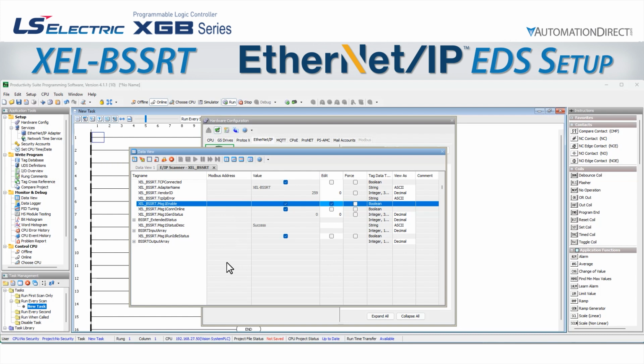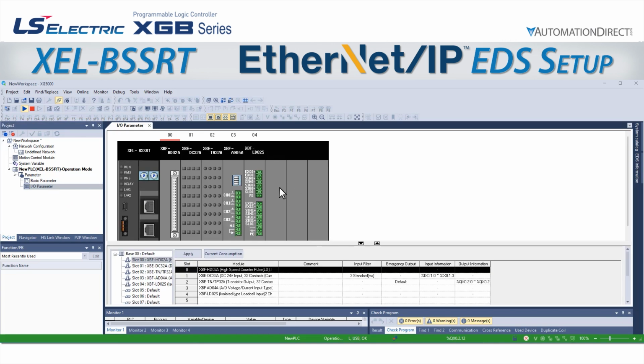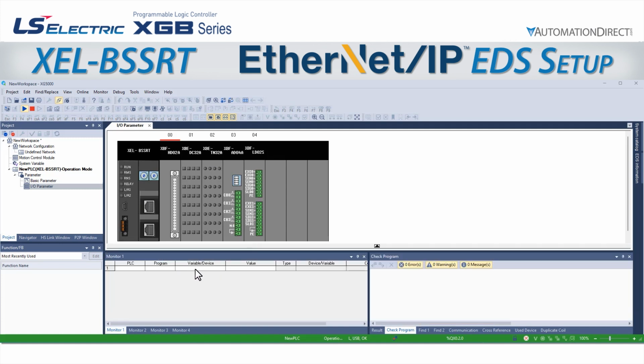Let's try and turn on the first output of our digital output card. If we go over to XG5000 and then to the I/O parameters screen, which is already open in our case, we see that the TN32A output card is in slot 2, which is the third slot, and that the first output point is variable %QX0.2.0. Let's add that to the monitor window so we can observe when the module turns it on and off. We will also go into monitor mode, and we see that the output point is currently off.